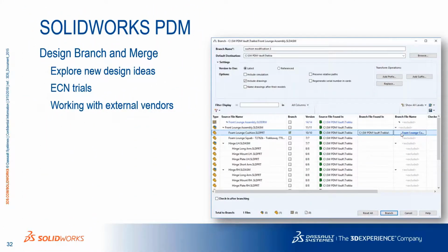Now, a new feature with PDM is the design, branch, and merge. This really allows you to explore new ideas, because what you can do is take a part, especially from an assembly, and you create these branches. What these branches are is it just duplicates the geometry, but it breaks all the references to the assembly. Now the assembly is still intact and the original part file is still there.